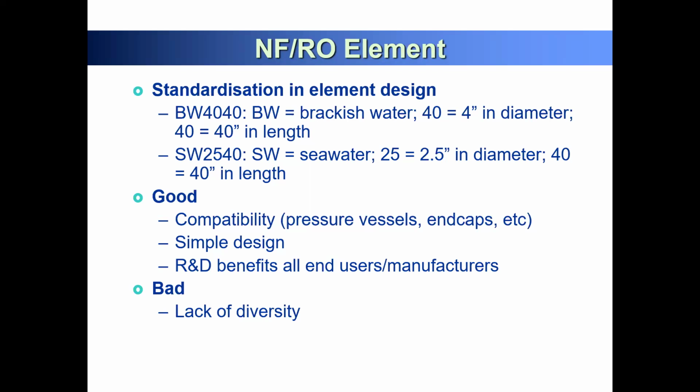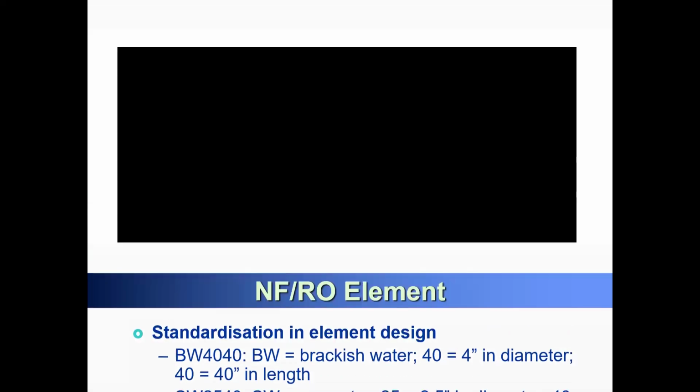In the software, there are around 25 membrane elements from the Wave software. So you can select, okay, I'd like to use SWR for our design, this membrane is best for me. So you can pick one of the membrane module types and calculate from your design. That's how it works.